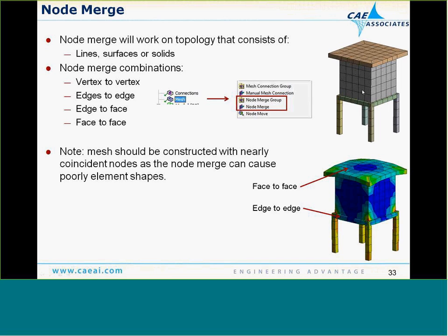One of the difficult things that you might see if you try to use this is that you need to make the mesh pattern match up between, let's say, the surface body, for instance, and the solid. And that isn't always the easiest thing to do. What I did is I imprinted the solid onto the face of the surface, so you see that that geometry does look the same between both, and then I could put on consistent mesh controls to get the nodes to line up in there.